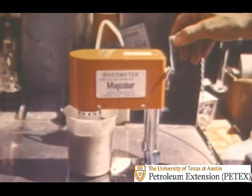Then, to obtain a more scientific measure of the mud's viscosity, the mudman uses this instrument. It's called a rheometer, a rotational viscometer, or a VG meter. It may be hand-cranked, as this one is, or may have a motor. In any case, a viscometer measures the mud's viscosity in terms of centipoises. A centipoise is a unit of measure for viscosity, just as an inch is a unit of measure for length.